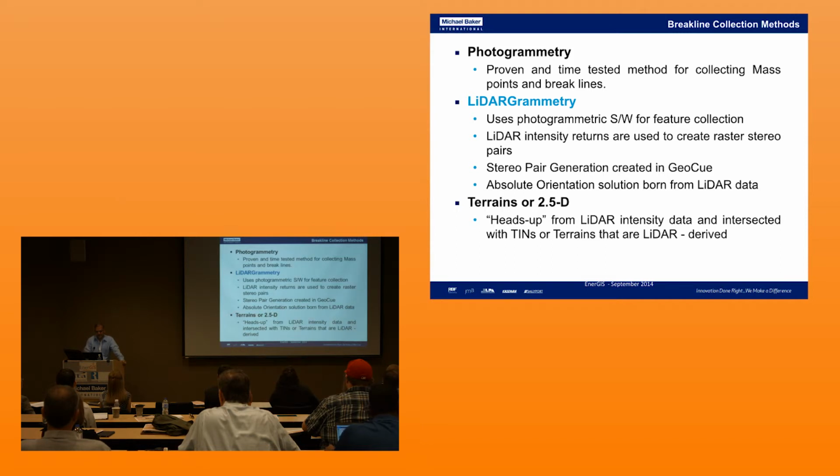And the other way of collecting the breaklines is what we call 2.5D. That means straight away you do the digitization heads-up without getting into the LiDARgrammetry. There are some advantages, but there are some disadvantages, by collecting 2.5D breaklines directly from the LiDAR intensity data.